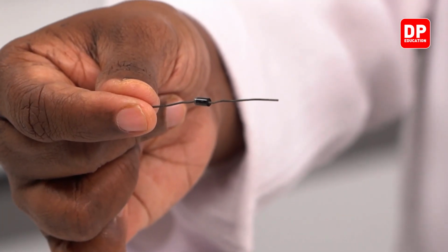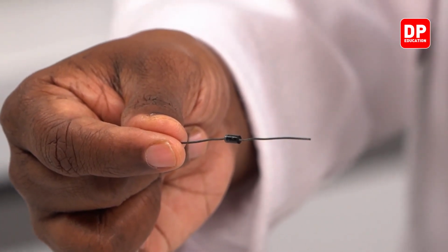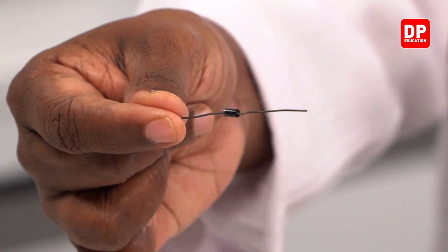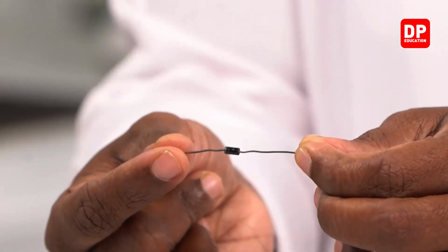So, when we use a diode, as we have already discussed, students, we always connect the P terminal to the positive terminal of the battery and the N terminal or the cathode to the negative terminal of the battery. That is how we use a PN junction diode. I'm sure you all can understand that. So, always look at the diode, look for the silver color band. If it is a PN junction diode, you have to look for the silver color or the white color band. From that, you identify the terminals. That is how we use a PN junction diode.